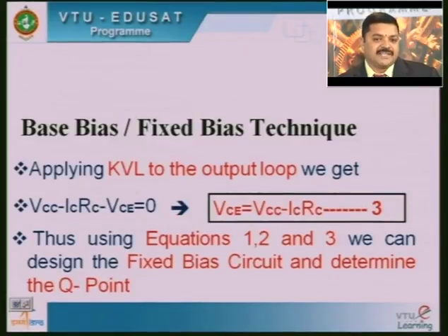So we got IC constant and VCE constant. Once we fix the operating point, IC and VCE will not vary, which means the operating point fixed at the center of the active region stays fixed there, or we can say it is stable there. Once we get a stable operating point, we get faithful amplification. But there are certain disadvantages, we will see that later.